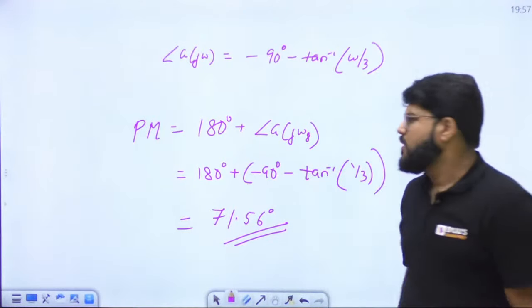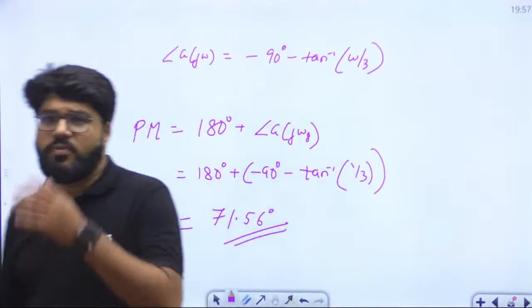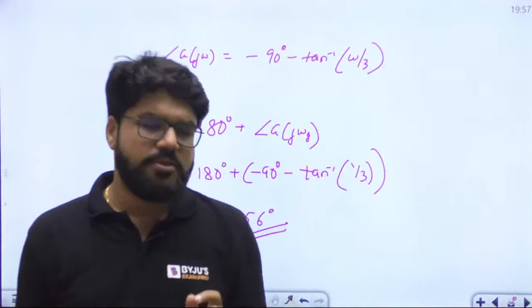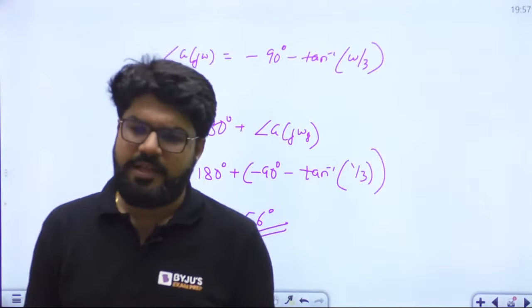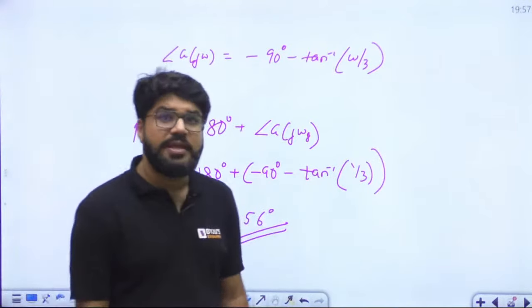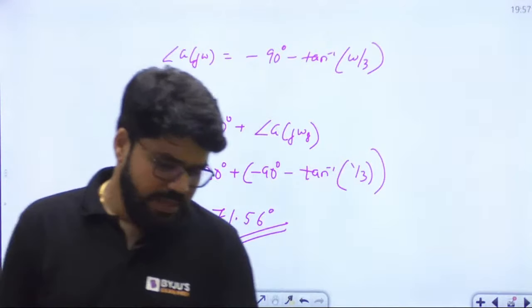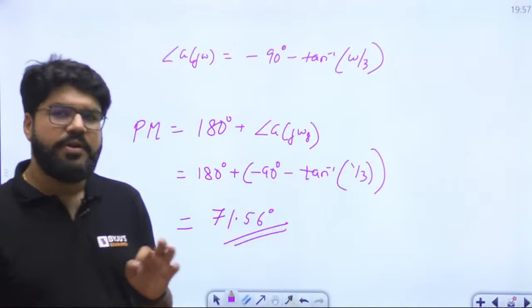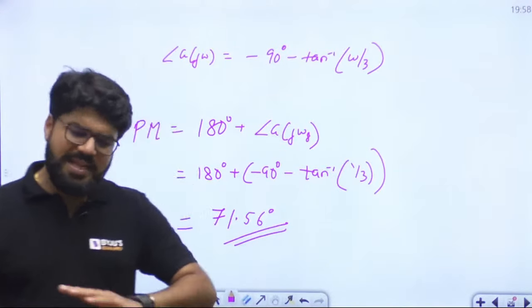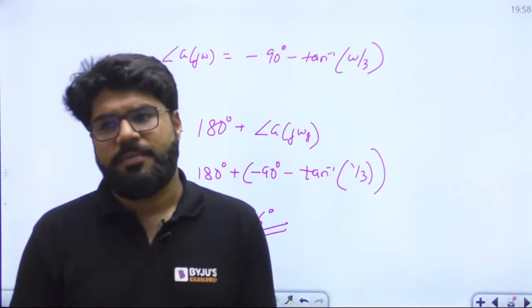The phase margin. Okay, so these are the different varieties of questions. Some precautions, as I told you with the last question once again: whenever there is no real gain crossover frequency, take phase margin as infinity. If omega p is infinity, then the gain margin will also be infinity in that case. And if omega p is 0, starting angle is the omega p, then don't trust the GM formula. 2-3 precautions, rest all basic formula based questions.